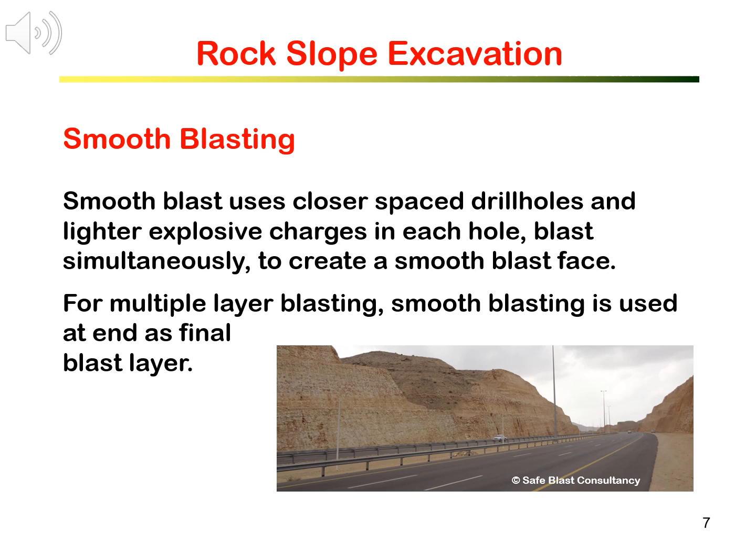Ideally, when we cut a slope from rock, we want, one, technically, the slope is excavated to be stable and require minimum support and be most cost effective. And two, aesthetically, the slope is looking nice and smooth. To achieve such high quality finishing of the slope, controlled blasting is often used by means of smooth blast and pre-split blast.